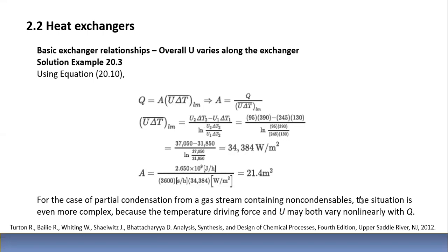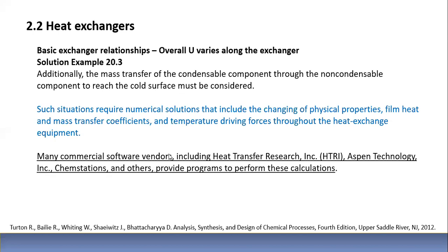For the case of partial condensation from a gas stream containing non-condensables, the situation is even more complex because the temperature driving force and U may both vary non-linearly with Q. Additionally, the mass transfer of the condensable component to the non-condensable component to reach the cold surface must be considered.